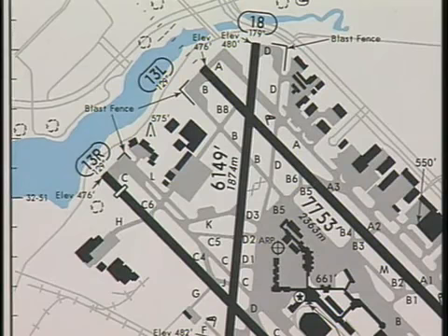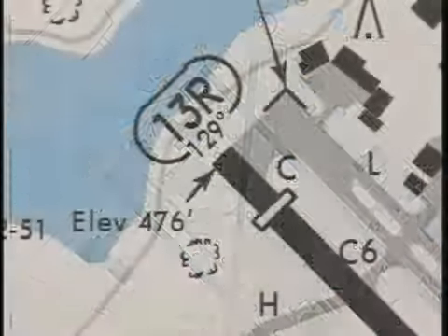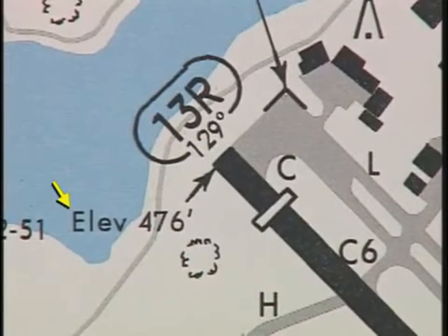The airport diagram depicts the layout of runways and taxiways. To avoid confusion, the runways are shown in black, while taxiways and ramp areas are printed in gray. The runway number, the runway elevation, and when available, the exact runway magnetic bearing are depicted on the ends of the runways. There are several symbols included in the plan view to help better orient you with the airport environment.